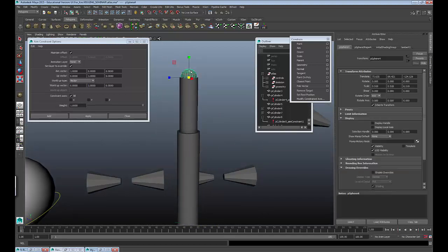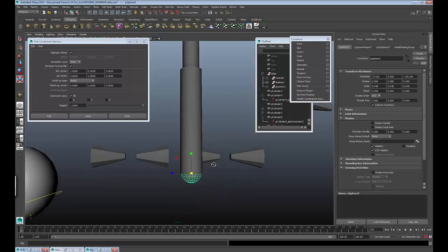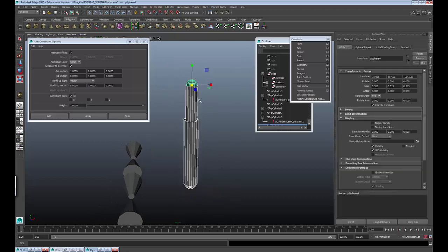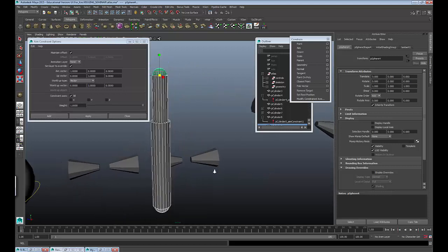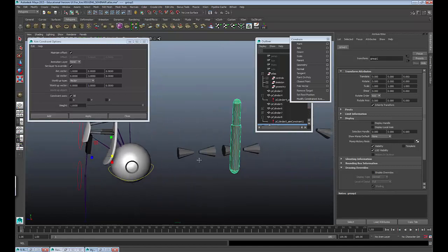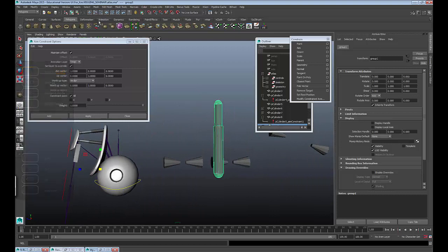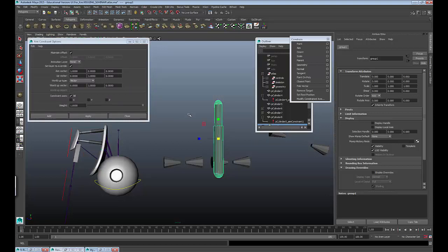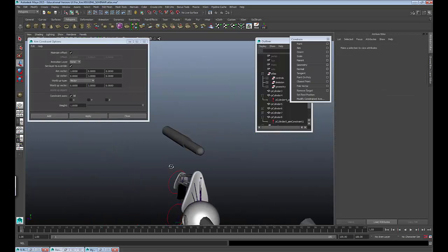All right. So these are going to be the pivot points, and then so even if there's an angle, it doesn't really matter if you freeze transformations. The key thing, though, is to make sure your pivots are always aligned to the center of your object where you want things to move from. So I'm going to freeze transformations, delete history. I could even, like the arm here, kind of move things around and rotate them into position if I needed to. So I'm going to group it to itself, maybe center pivot on the group, but not center pivot on the geometry itself, because that would mess up my pivot points. So maybe I'll just kind of move it like this.